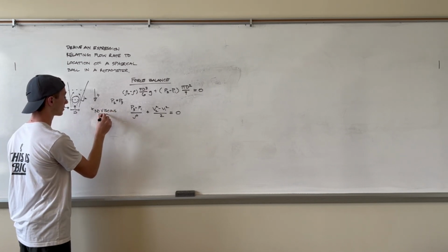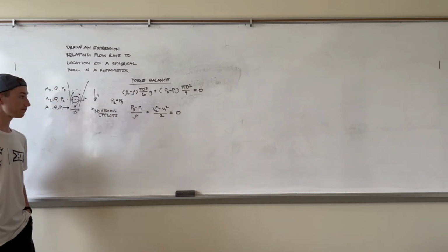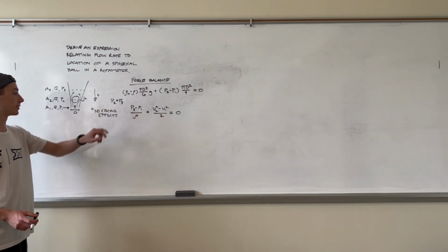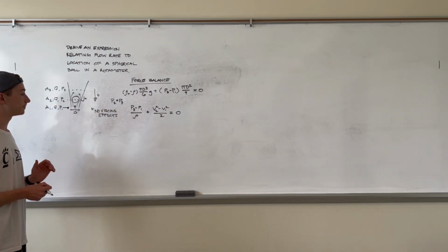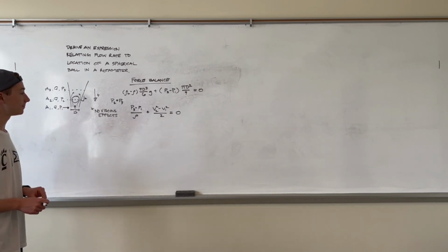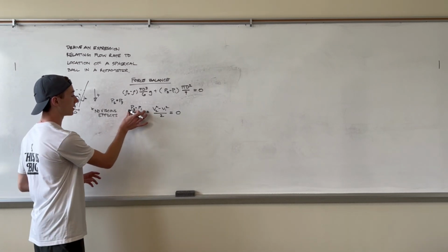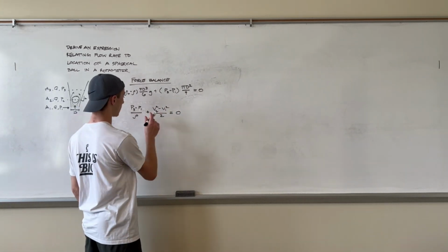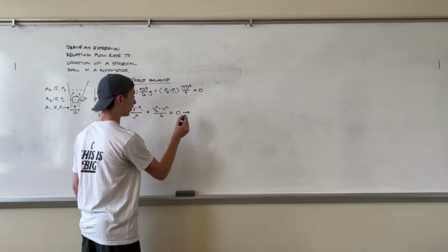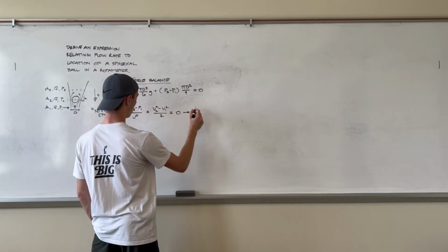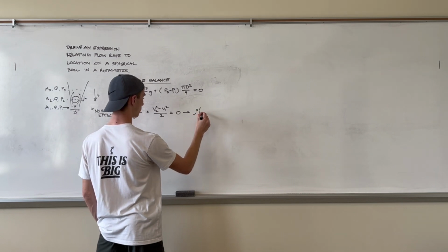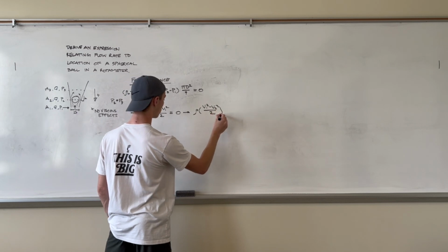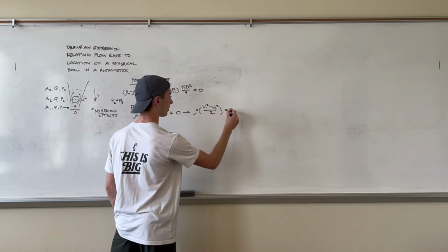Viscous effects of fluid, right? Okay. And you'll notice that I'm using V2 and V1 in 1 and 3 because we said that P2 is equal to P3. Okay. So we have this expression now. And you'll notice that we have P3 minus P1 here, and we have P3 minus P1 here. So what we can do with this is isolate P3 minus P1. We get rho times V1 squared minus V2 squared over 2, right, is equal to P3 minus P1.